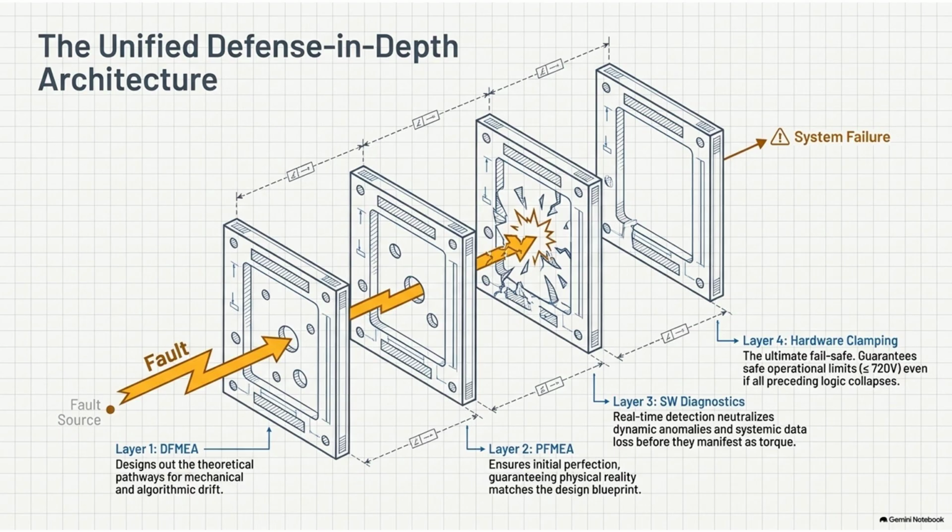You can't safely test the limp home mode and that 720-volt stepwise ASC parachute by driving a prototype car at 80 miles an hour and throwing a wrench in the motor. No, that would be lethal. Instead, they use HIL, hardware-in-the-loop fault injection. This is the digital torture chamber. They put the motor controller on a bench, hooked up to a real spinning motor running at 12,000 RPM under absolute full electrical load. It is pulling maximum current.